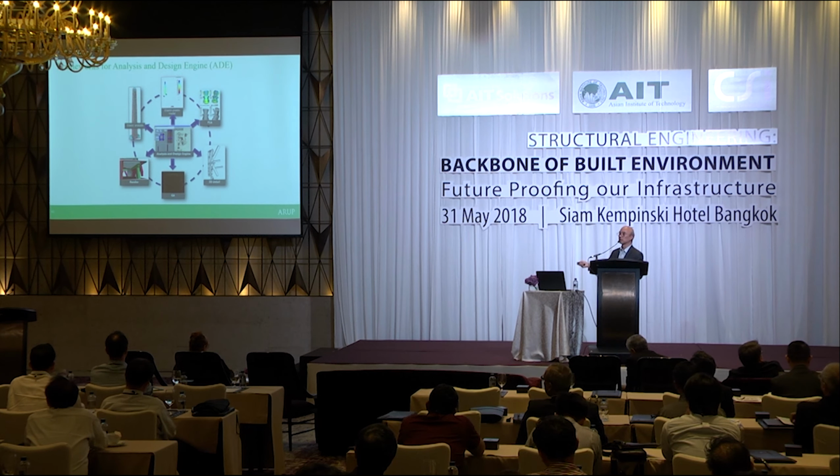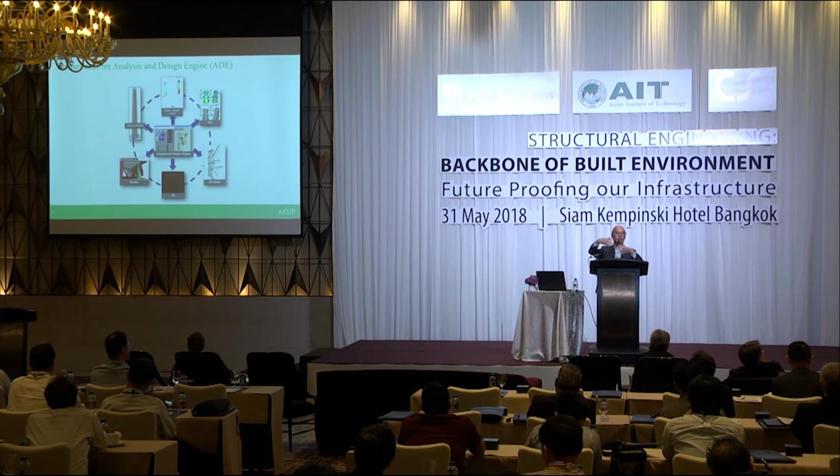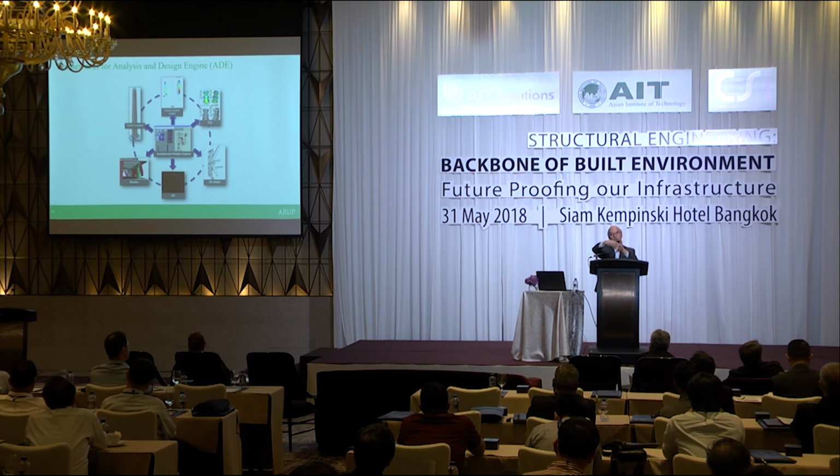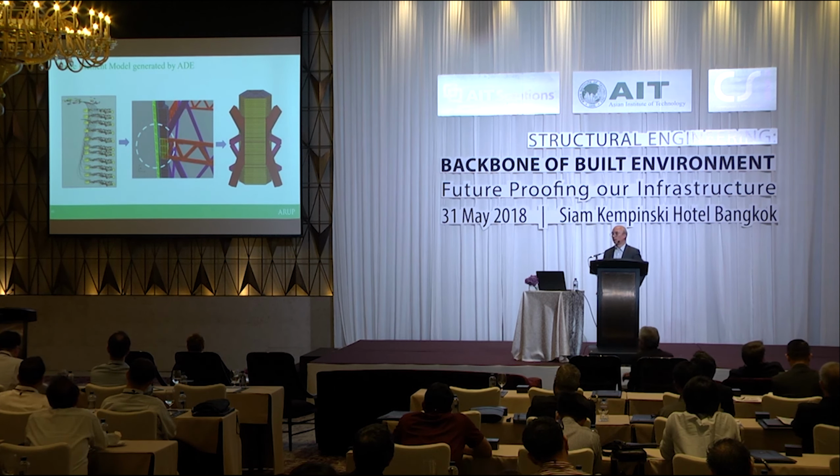joints, right? This is very important because again, when we design, the building design changes, and the angle of bracing may change, and so forth, and all these make the connections and all the shop joints need to change. All the connectivity, the cassette plate, the stiffener, and so forth and so on, all these relationships are interrelated. Right? So you change the angle of bracing, you change a whole lot. So with all this parametric technology, we can now link it together and make life easier.